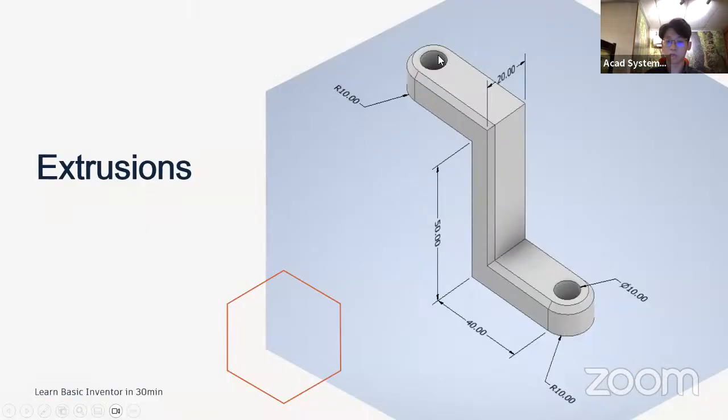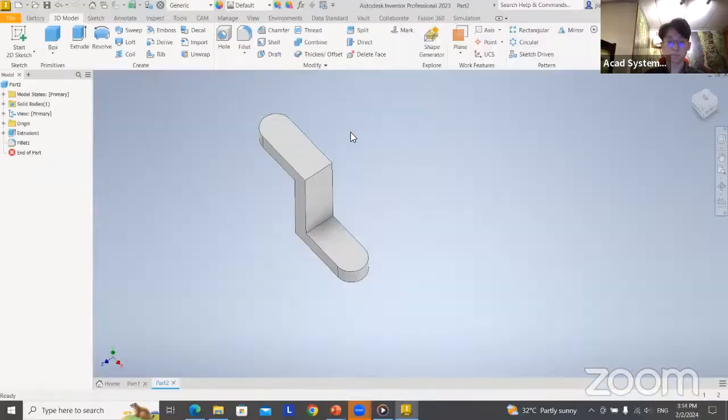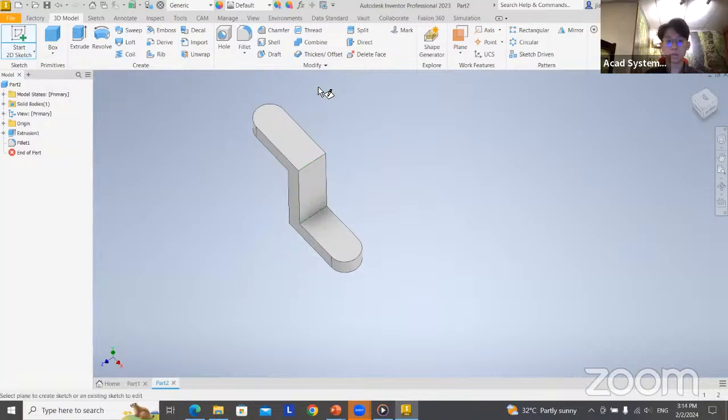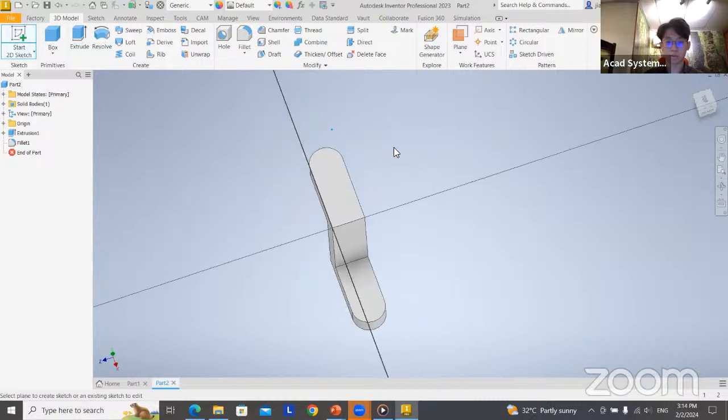And after that, how do we draw this circle hole on this extrusion? Basically, same goes for every extrusion. Start with a 2D sketch. But instead of showing us the plane like just now, we're going to select the surface plane over here. Click on it.